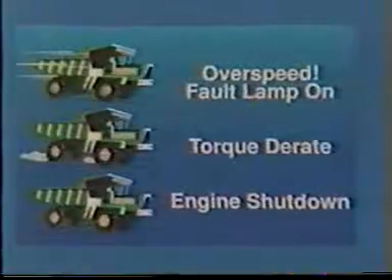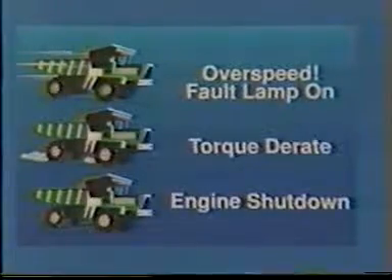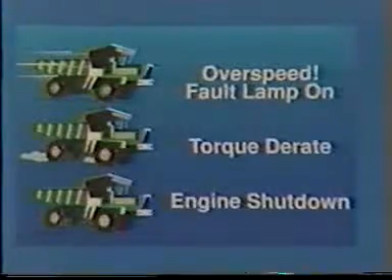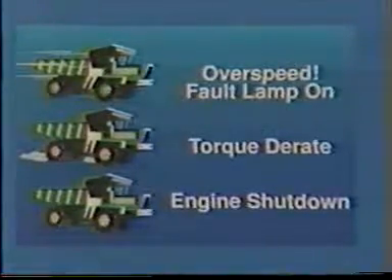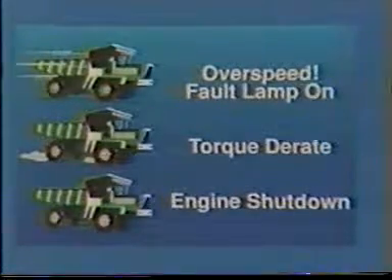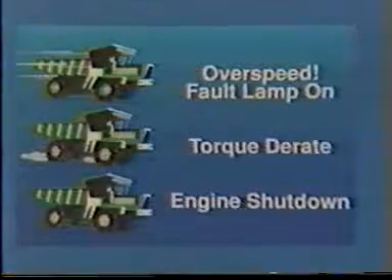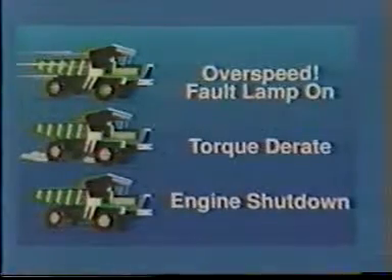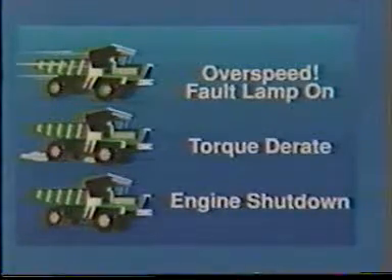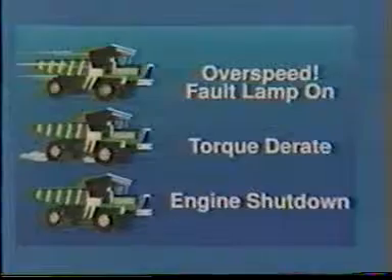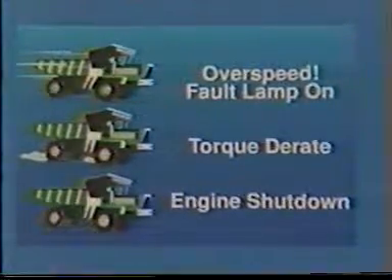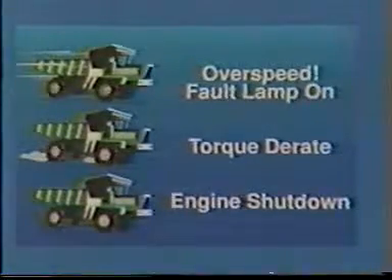After turning on the engine protection lamp, the ECM starts recording elapsed time and monitors the severity of the event. If either duration or severity exceed a pre-programmed value, the ECM initiates a torque and/or speed derate. After a derate is initiated, the ECM will continue to monitor both duration and severity and will shut down the engine if the condition is not corrected. The engine shutdown feature can be overridden through OEM calibration options.